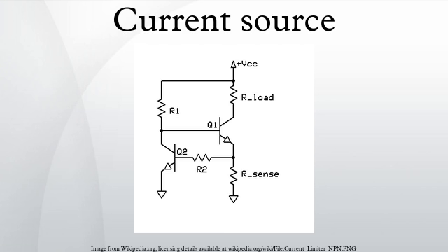Active current sources without negative feedback. In these circuits, the output current is not monitored and controlled by means of negative feedback. Current-stable nonlinear implementation: they are implemented by active electronic components having current-stable nonlinear output characteristic when driven by steady input quantity. These circuits behave as dynamic resistors, changing their present resistance to compensate for current variations. For example, if the load increases its resistance, the transistor decreases its present output resistance to keep up a constant total resistance in the circuit.